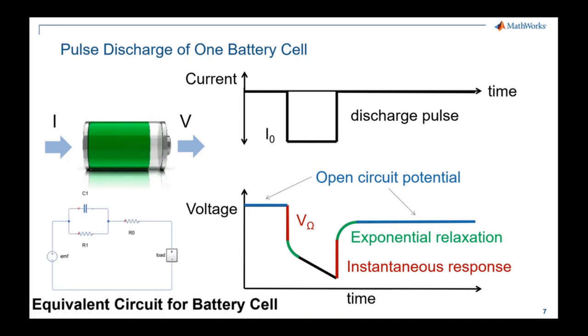So in our case, we have a lithium-ion battery that works following a chemical process. And here what we can do is create an electrothermal analogy to this process that is called an equivalent circuit. And that's what you see here in the lower left corner. Basically, we can model the chemical process of a lithium-ion battery by having an internal voltage source, which is this EMF here, an output resistor, which is R0, and a pair of resistor and capacitor that is our RC branch of the battery. And now we will go a bit more into detail regarding these parameters.